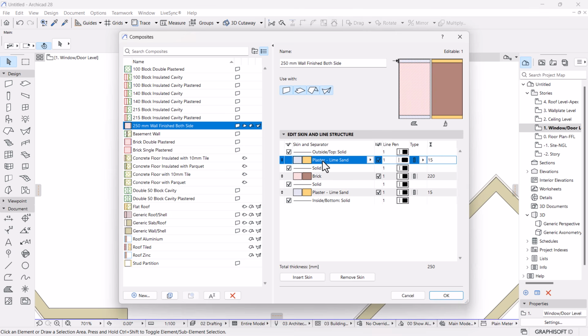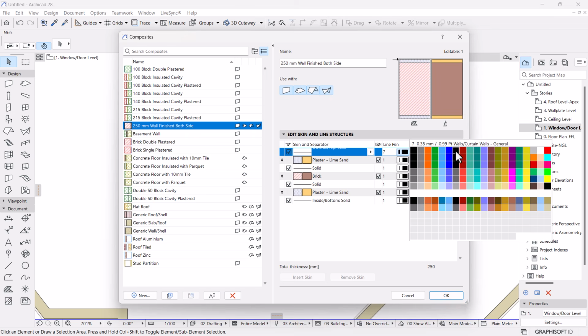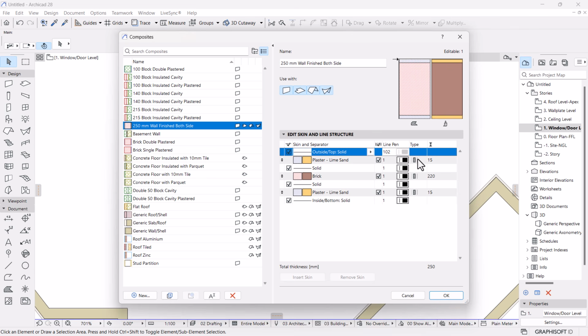And the interesting thing is when you select this element, it indicates where it is located on the preview here. Okay, so what we've selected is the outside top line, which is this one. We can change its weight, let me use a gray color for general drafting, for an example, and do the same to this one, which is 101. I'm going to type 102 because I can reference with this one, and then also this one is going to be 102. Let's make these two the same.